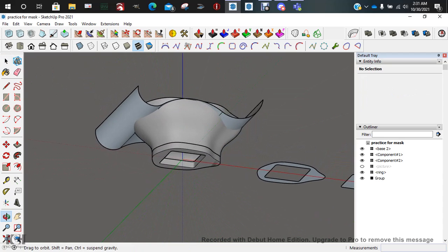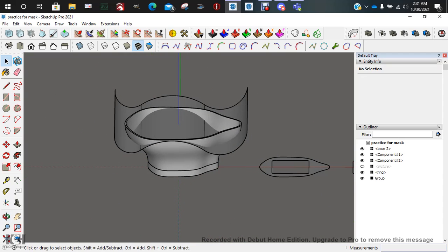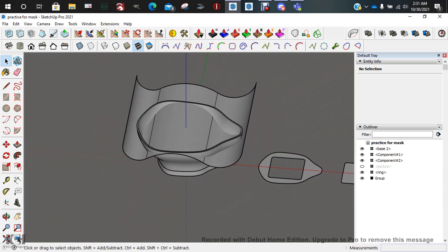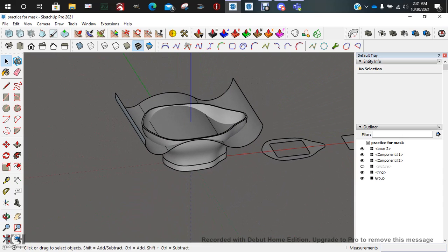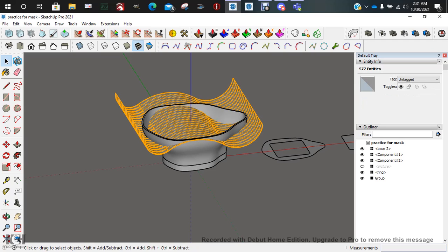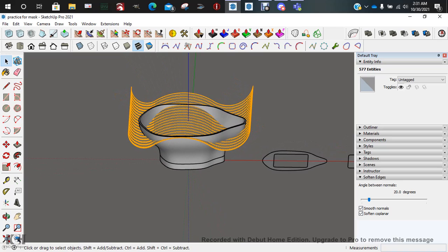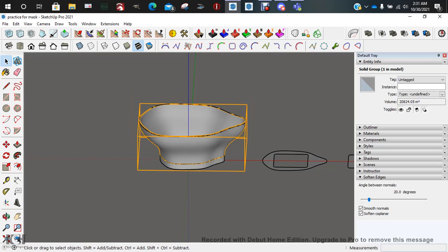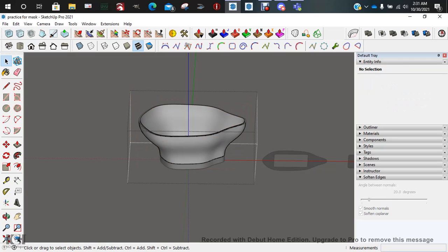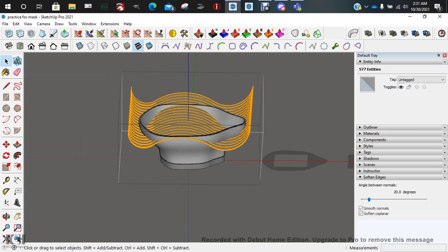Okay, this operation can be a bit slow for some laptops like mine. It takes like 7 minutes. But what you're going to want to do is, let's triple click that. I'm going to soften it. There we go. Okay, now that it's softened, I'm going to cut it again. I'm going to go inside the group and I'm going to go edit, paste in place.